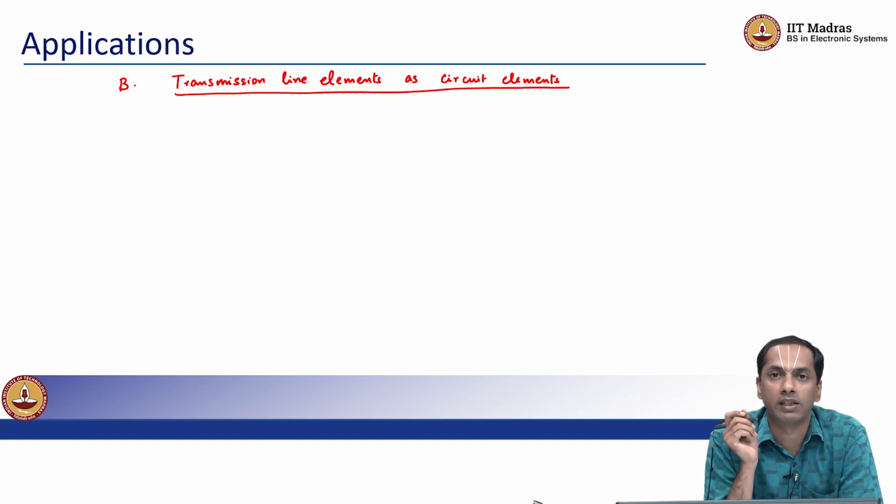But nevertheless, there are these challenges when it comes to building capacitors as we know them in the toy models. They tend to have these additional concerns, which is that the leads attaching the parallel plates to the circuit itself are now relevant at high frequency operations.